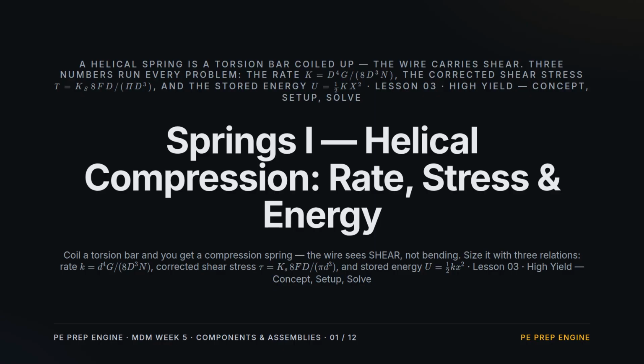Week 5, Lesson 3, Helical Compression Springs. Vessels and cylinders held pressure. A spring stores it. Picture a straight torsion bar wound into a coil. When you push on the coil, every bit of wire twists, so the wire carries shear. 3 relations run every spring problem: the rate that sets how stiff it is, the corrected shear stress that decides if it survives, and the energy it banks. We build all 3, then work a full example.